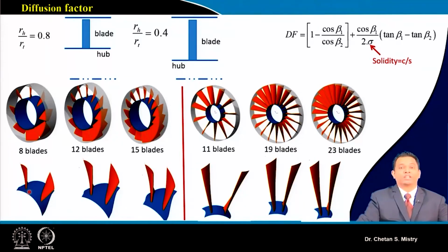Okay, so the next option will come with the increase of number of blades. So suppose here we are increasing our number of blades. Yes, this will give you high pressure rise, or the pressure rise we are expecting. But because of the presence of more number of blades, the losses are going to increase. Those losses are frictional losses, and that will lead to reduced efficiency. Okay, now in this case, suppose you consider we have our hub to tip ratio in the range of 0.4.